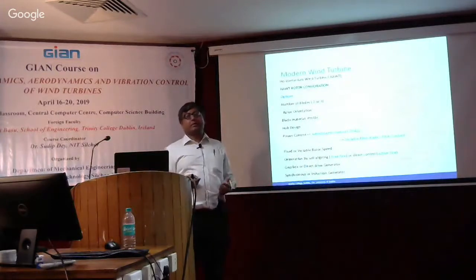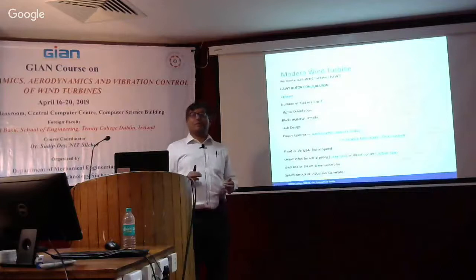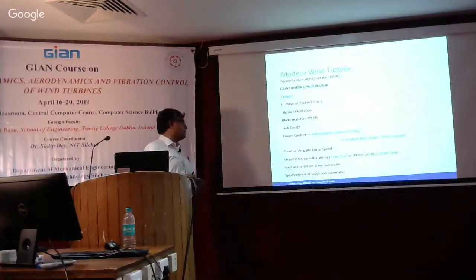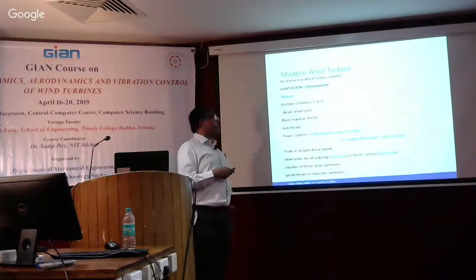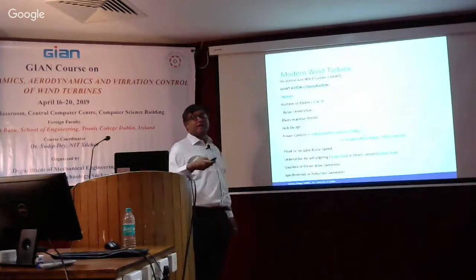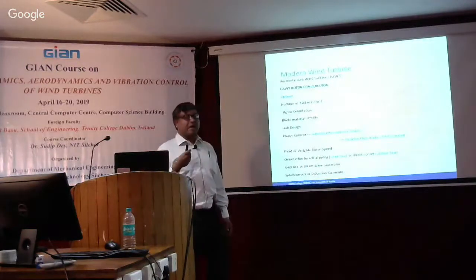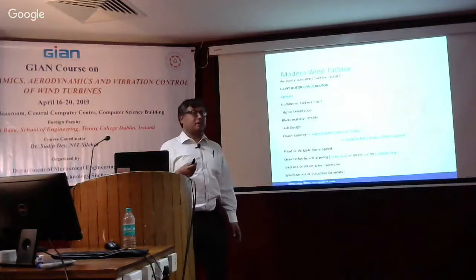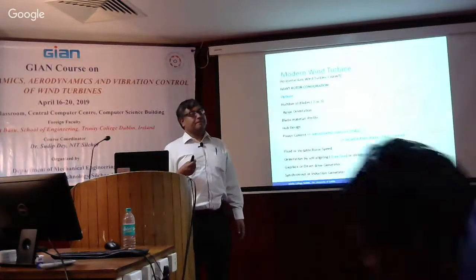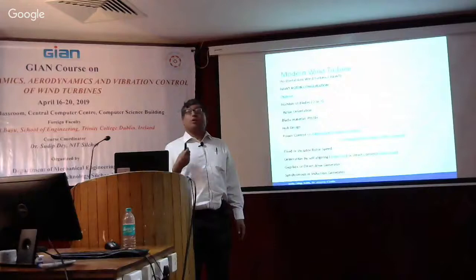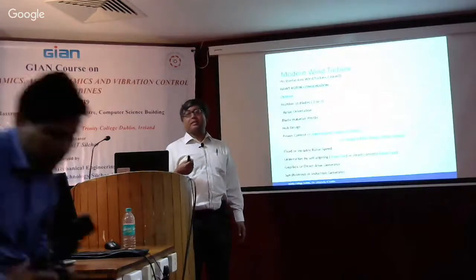This is a particular manufacturing procedure they're using for blades. The profile resembles airfoils, so you have the NACA profiles, and typically those are also used here. But mainly the characteristics which guide the design of a blade are the power coefficient, and essentially that means the lift and the drag.